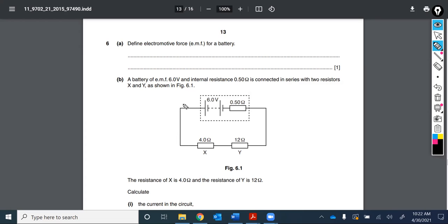the charge is doing work in the resistors, but even if there's internal resistance, like we see in this example down here, the total work done, even the work that's lost, not doing useful work, but the total work done. So the textbook definition for e.m.f might be something like the total work done per unit charge. Work and energy are the same thing. You can think about this lots of different ways. In general, voltage is energy per charge, and e.m.f is a type of voltage.